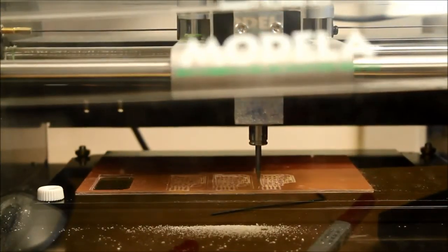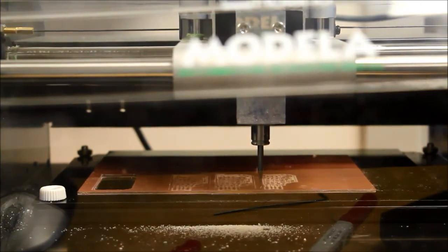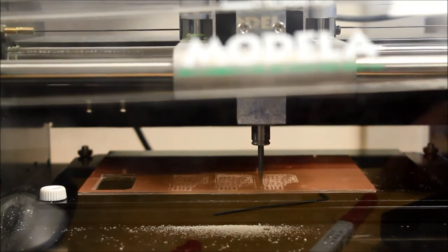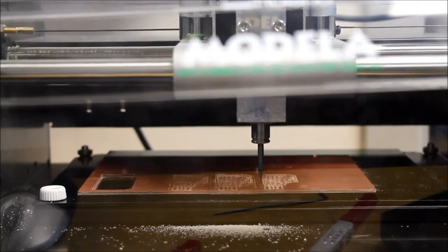And begin mill. It's actually going to cut deeper this time with each pass, so expect a lot more dust, and just listen for tool chatter. If you hear tool chatter, you can turn the machine off directly with the button on the machine, or actually click the abort button on the computer. So I click begin milling, and it's going to begin here in just a second.